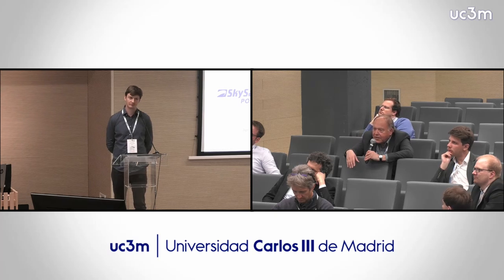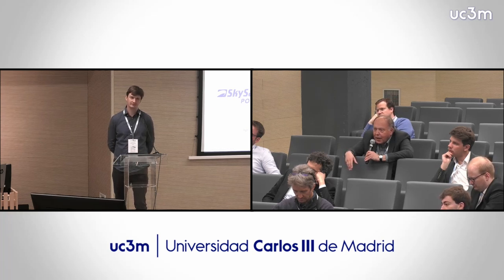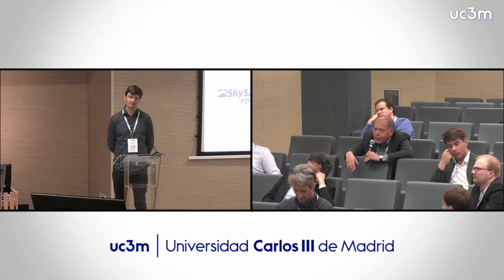The panel method would still not be able to compute the separation of the flow on the extrados of the wing, because the panel method, by definition, assumes an attached flow everywhere. Indeed. So the intake is a problem, but even if you solve it, you still have the problem of the boundary layer separation on the top of the kite.